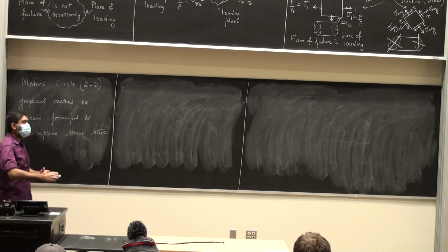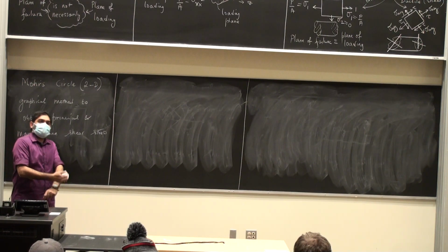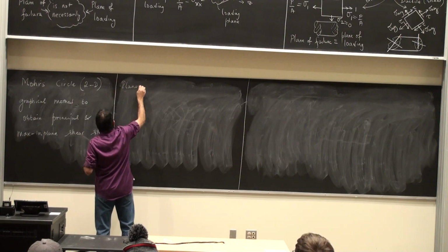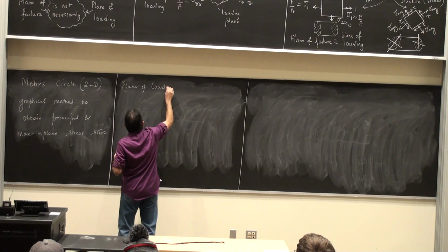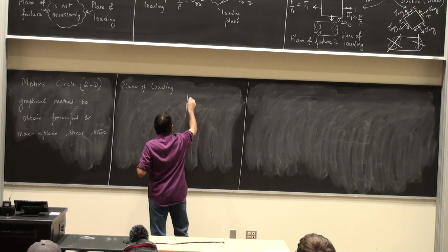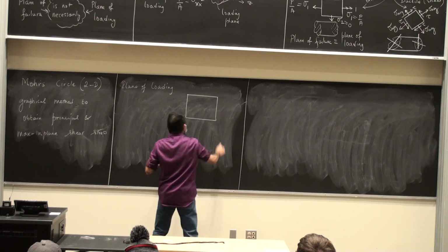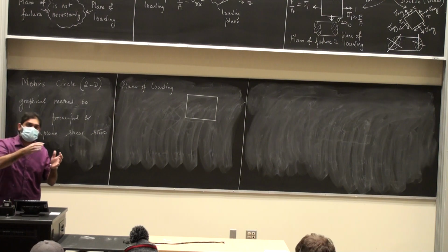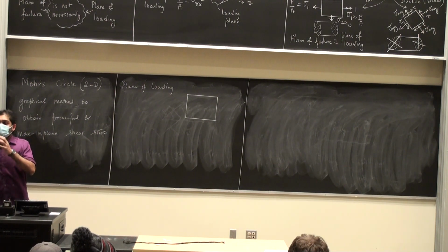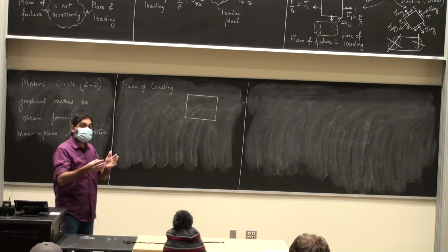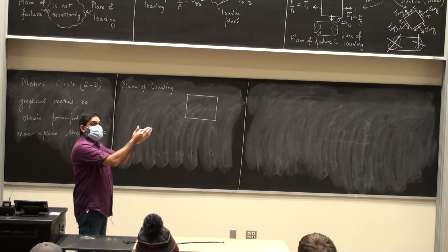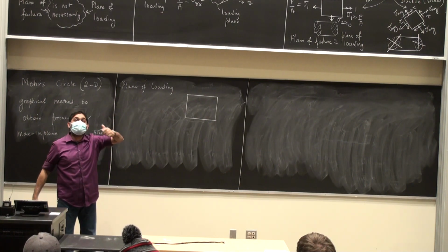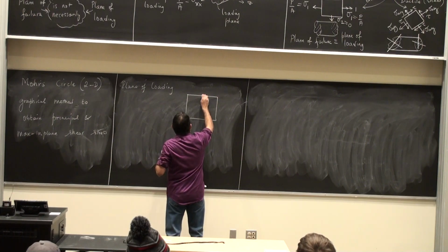All right. So what do you do in this problem? You start off with the plane state of stress on the plane of loading. What you would have done is you would have drawn the shear force and bending moment diagrams. You would have drawn the state of stress on the area element, removed it out, drew the state of stress on the volume element, set up your view, and crunched the three-dimensional cube to 2 dimensions. Then you would have ended up with the following state of stress, and that's what you're going to be seeing on Friday. Problems. Okay?